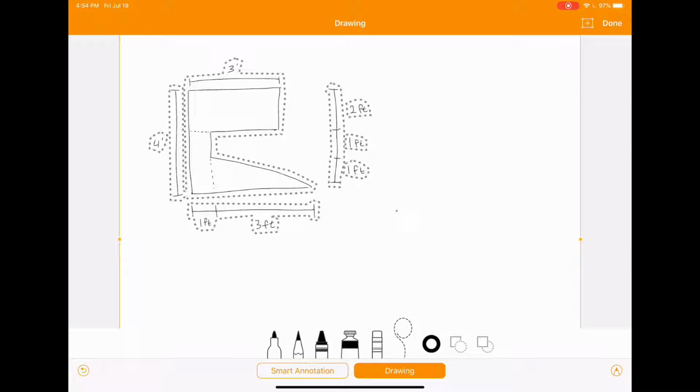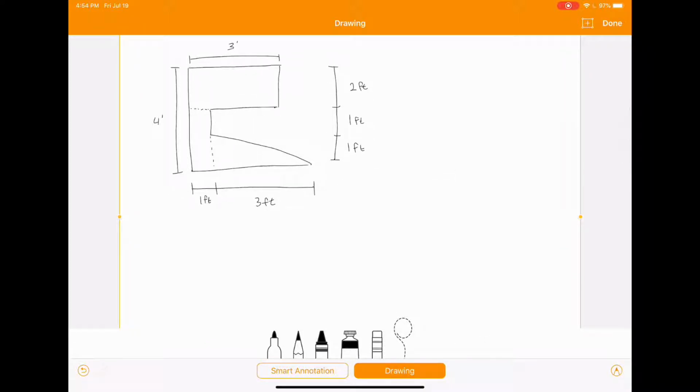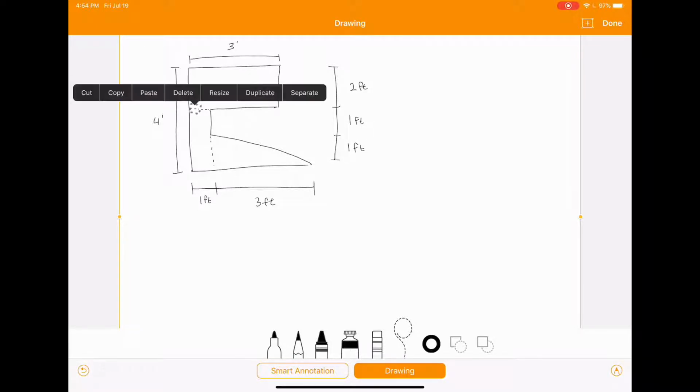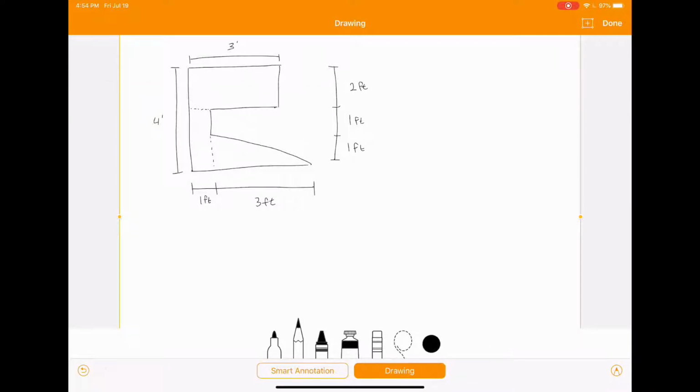All right. So this is our shape and we need to find our X bar and our Y bar. Like I said, the first thing we want to do is separate this into individual shapes that are easily recognized, and then we'll number them. So 1, 2, 3. For our overall shape, we've got 3 different shapes within that shape.